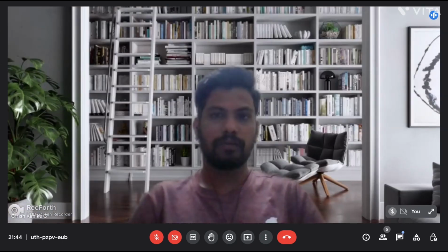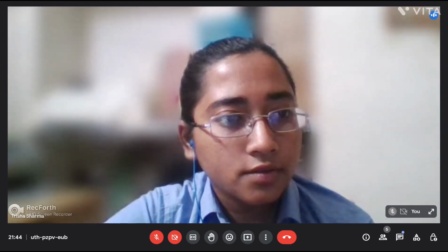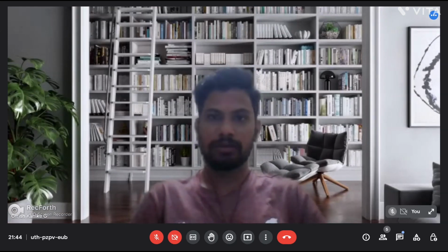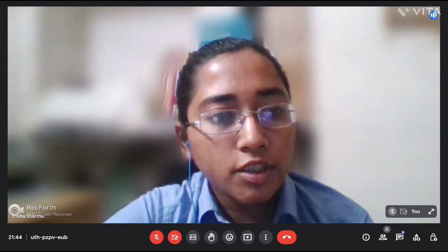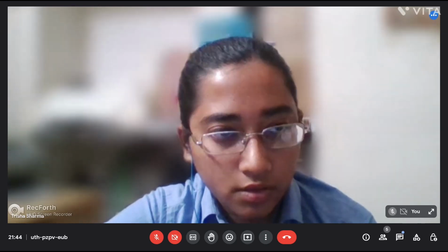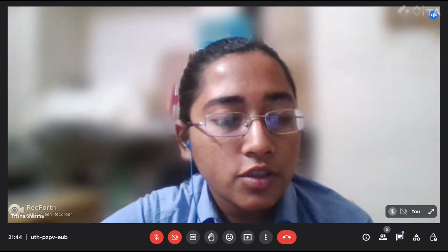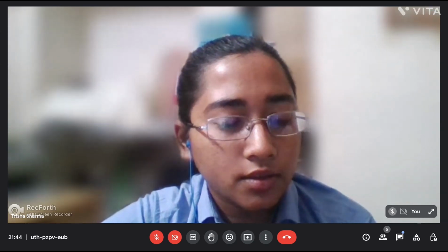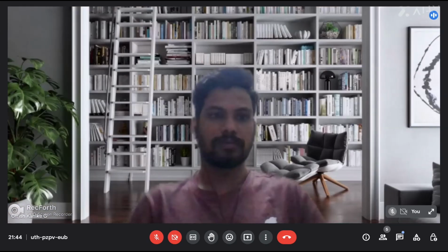We need 2 select lines. Okay. If I have to design 8:1, 3 select lines. So how do you say that you need so many select lines for so many inputs? Because for 2 to the power n inputs we need n select lines.